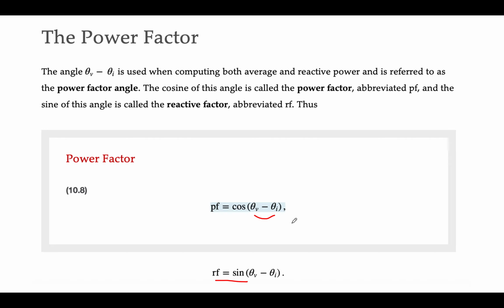So when you look at things like transformers and motors and other devices that you buy commercially, you'll see ratings or specifications on those. And many times the specification will indicate the power factor. So what that means is, whatever you're purchasing, let's say a transformer, you're not going to transmit 100% of the power to your load if the power factor for that device is less than 1.